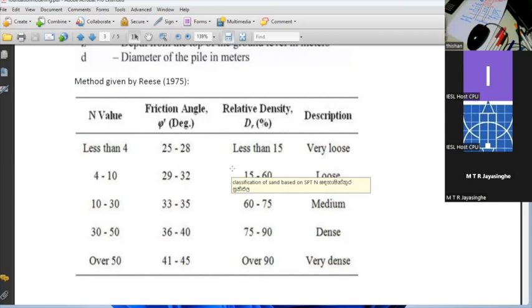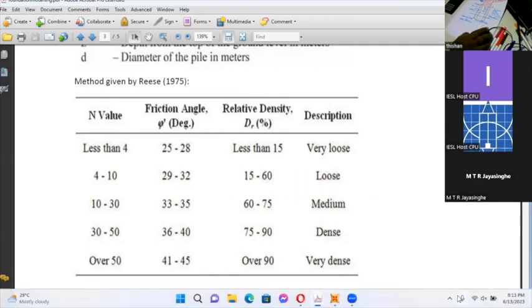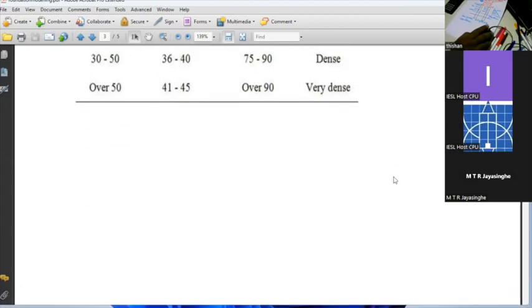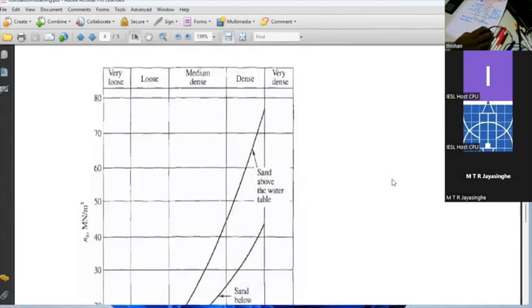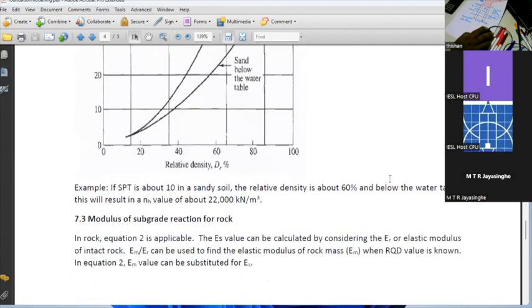And also for laterite soil, you will always look at whether the water table is high or low. If it is high, you will consider it as a clay soil. If it is low, you will consider it as a sandy soil. So I think we have covered a reasonable ground on that.